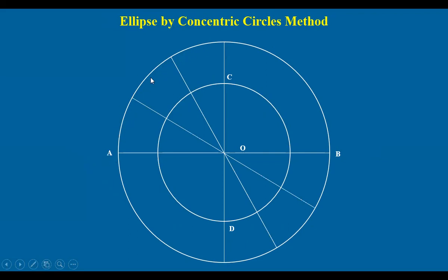So here I am dividing into 3 equal parts. That's why I have drawn diameter lines. That is also dividing this part of the quarter circle. Now let us mark this point, where the diameter line intersects, as 1, and 2, and of course, because we have made 3 equal parts, we mark the third point also.